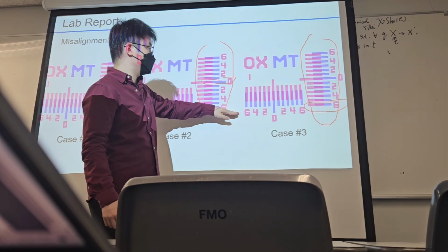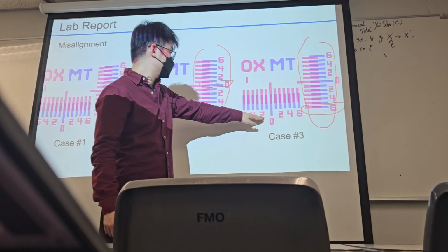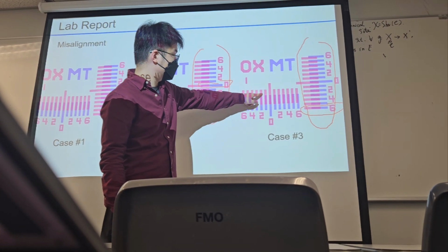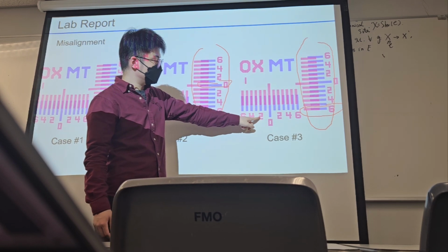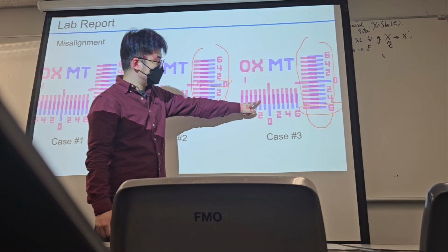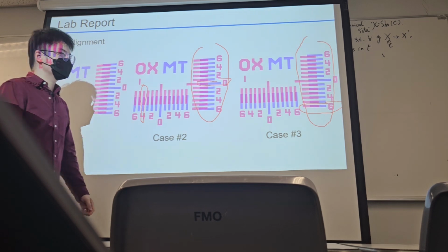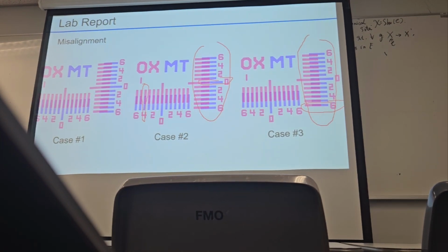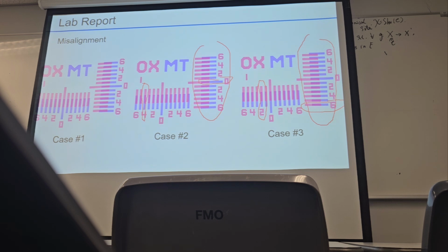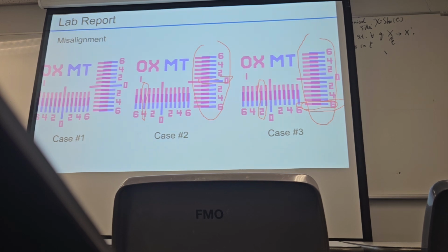Then for the lateral, here, the ruler for the 2 is the perfect alignment, no misalignment between these two rectangles. Which means the lateral misalignment is 2 microns, right? So you can read the misalignment directly. And I think some of you made a mistake in your lab report.